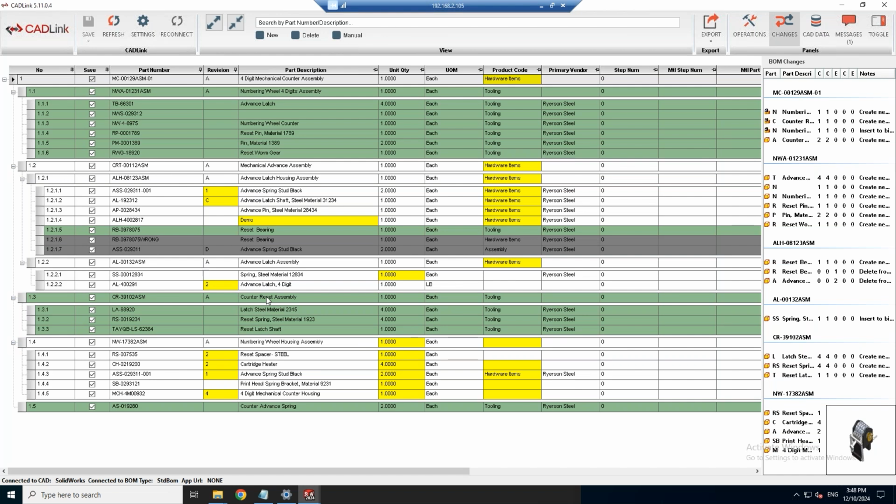The manual part feature can also be used to add parts to your XA bill of material without having to model it in SOLIDWORKS or include it in your CAD, PDM, or PLM designs. This is especially useful for consumable items, for example, like paint, glue, fasteners, bolts, hardware, packaging, anything that you wouldn't necessarily model in your engineering systems, but you do need in XA for purchasing or manufacturing reasons.